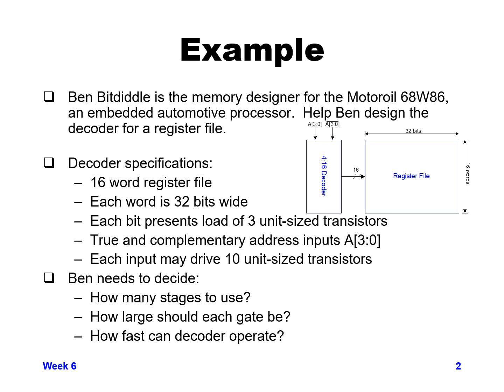And each bit represents a load of 32 unit size transistors. So that would be equivalent, a couple foils ago I was saying that the minimum size inverter would be a size 2 PMOS and a size 1 NMOS, so unit size 3. So each bit represents having a load of one minimum size transistor or inverter, for example.